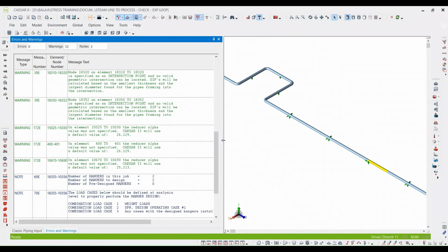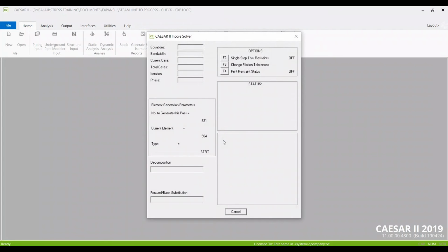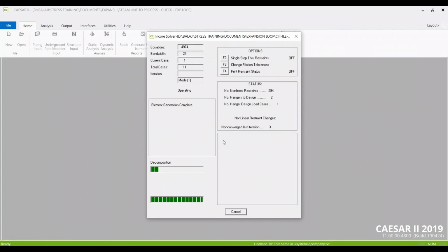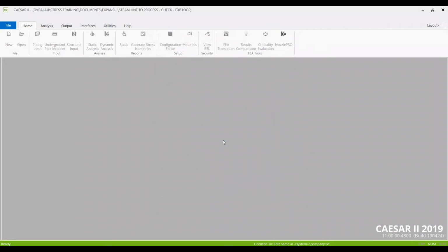And I will tell you how to model the lines on the pipe rack. It is very simple. So don't go one by one. If you know the overall length of the entire line in one stretch, you can model it and break it into a number of elements. Like that, if a support is there every 6 meters, you can break it into every 6 meters, and then add supports accordingly. And if you want to change in between, then you can check one to one.